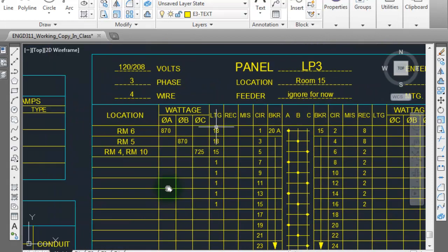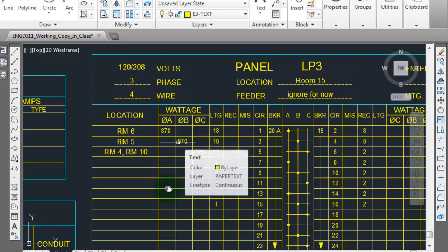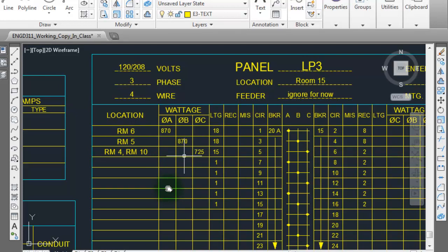So you're going to take the total number of lights that you've used, multiply by the wattage of those lights. Now keep in mind that we do not have all 48.3 watt lights. If you're talking about the corridor or the hallway, they're 51 watts, I believe, for the compact fluorescents. And the metal halides in the workshop are 250 watts. So you're going to have different phase wattages all the way down, also depending on the number of actual luminaires that you used in that particular room. So keep that in mind.